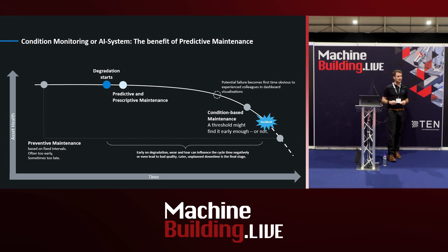But the reality is the product starts to have degradation at a very early stage, but you can't really notice it at this point. And the asset health, as that decreases, so does the subsequent performance. What we can do is provide condition-based maintenance. And this is in dashboards, etc., where you look at the data. This may be looking, let's take a pneumatic cylinder, at the air consumption of a complete line. You can start to detect it at that early point, though sometimes you might not meet it before the incident occurs.